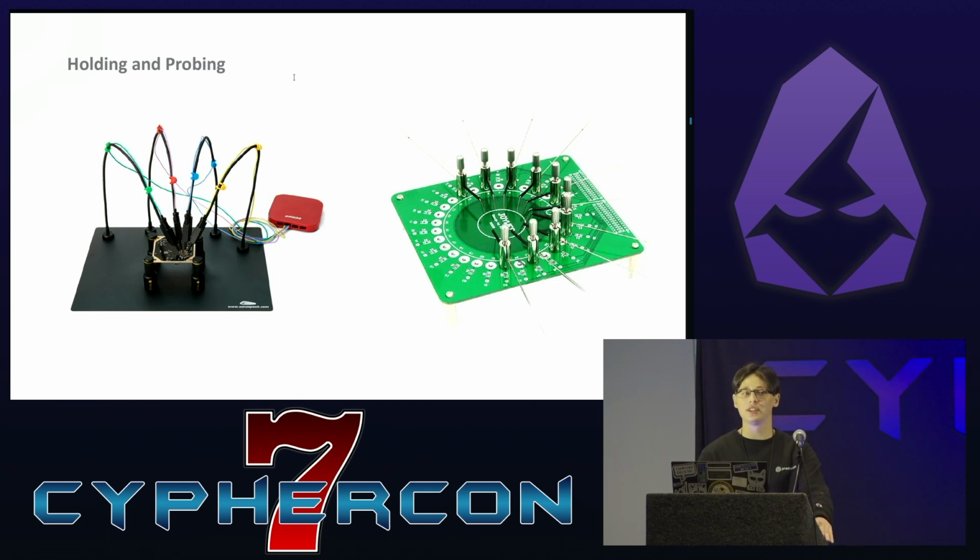On the left is a PCBite kit from SensePeak. It's a metal plate on the bottom, and then it has little standoffs that can hold your board. It's insulated, and then it's little adjustable arms. They have a magnet in the base, so they hold down onto the plate, and you can position them, and they have a pogo pin in the tip. So you can rest them on the pin or the test pad that you're trying to target, and then you have the leads off to plug into whatever equipment you're using. These are really great and can come in handy.